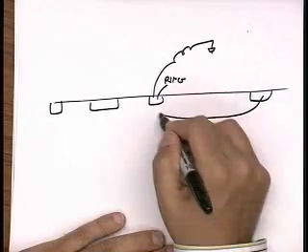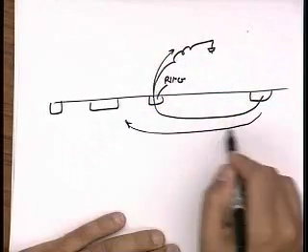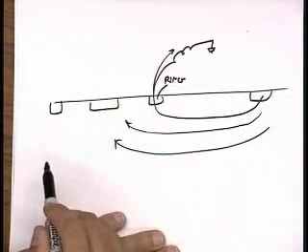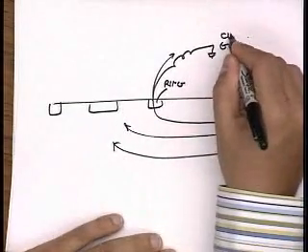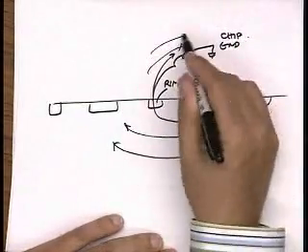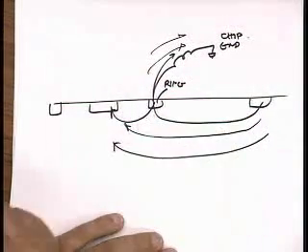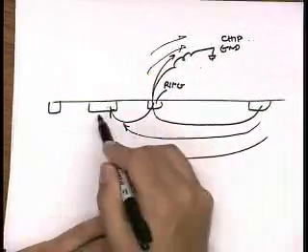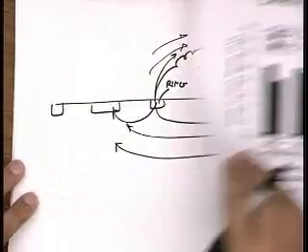So if I have an interference and it's going to ground, it's capturing some fraction, let's say 1 or 2%, maybe 10% of the current that's reaching here. But if I now tie this to the global ground, so chip ground, then there's lots of current going through here. So this is actually rippling, and this is acting like an additional noise mechanism. So it's taking all this noise, placing it close to your circuit, and injecting it in. And so things actually get worse.